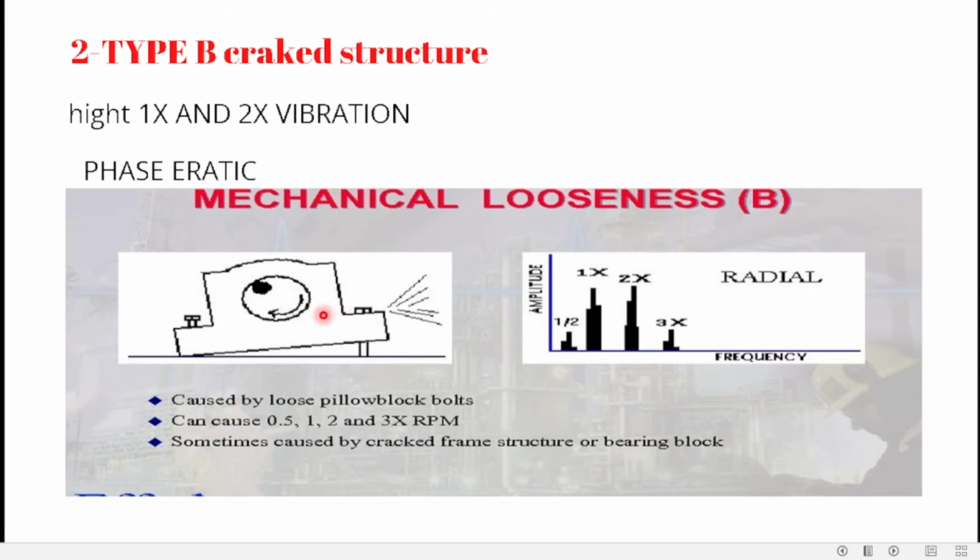We see in the bearing that this one is a crack or some other problem in the housing or pillow block of the bearing. In the FFT spectrum, we see 1, 2, 3 harmonics maximum to diagnose this problem of a crack.